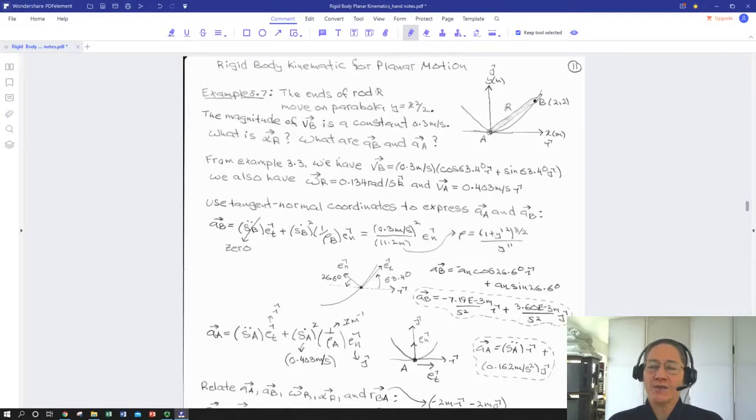And of course we can write an expression for a radius vector from B to A. So we've got all the components we need to deploy our acceleration of one point of a rigid body in terms of another, in terms of angular velocities and accelerations. This time we've only got one rigid body and the reference frame that contains our path, so we don't have the complication of a second.